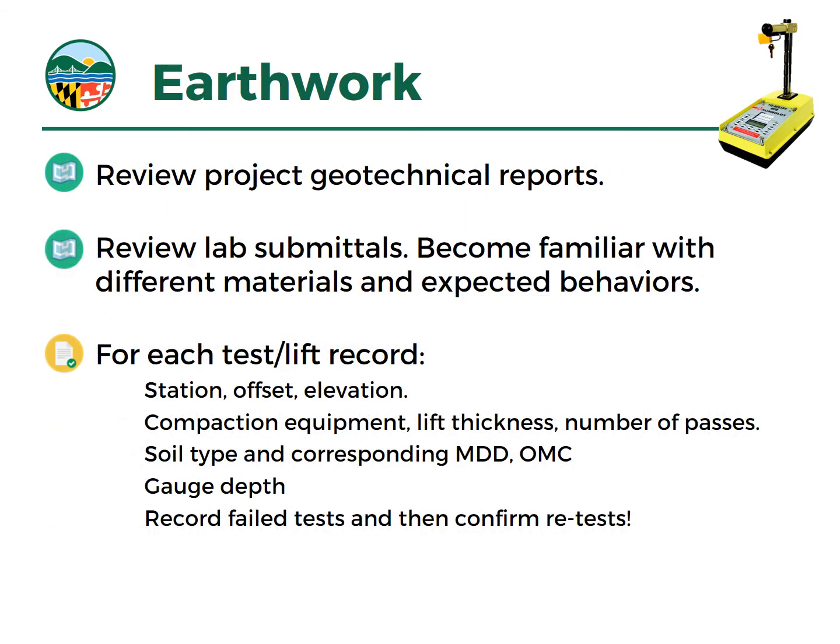So again, the inspector should review and be familiar with the geotechnical reports and the lab submittals, and know what to expect from materials on site, because a good lab technician and a good quality control technician is going to know what to expect once they've seen those lab tests. From experience, they're going to know the compaction characteristics, how these materials are going to respond to moisture, and they can be really valuable in that sense.